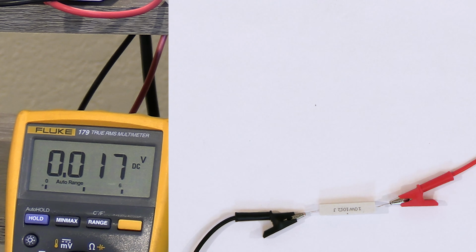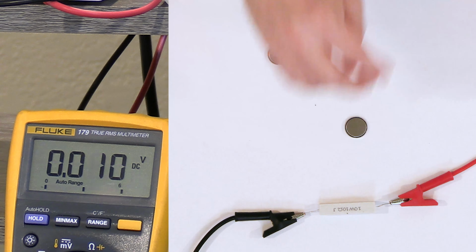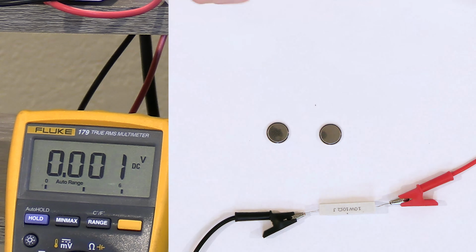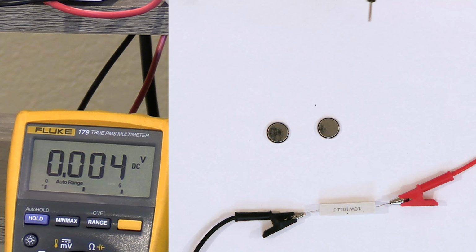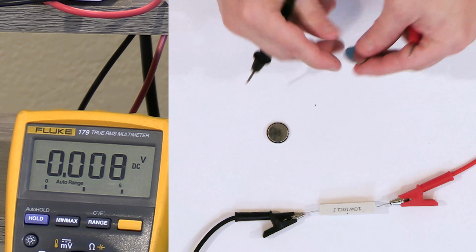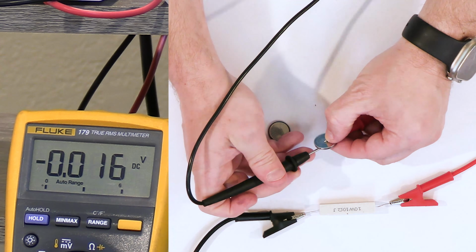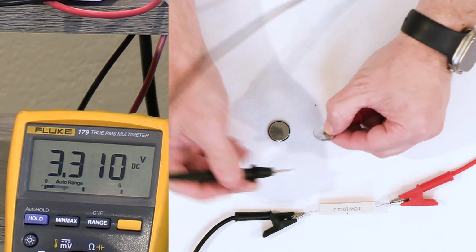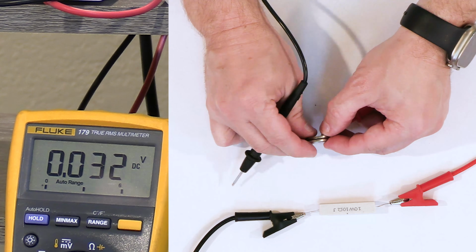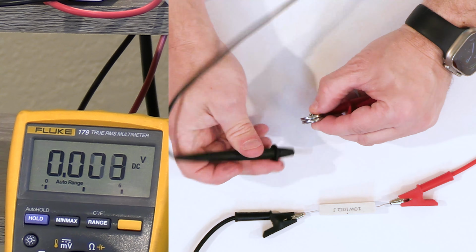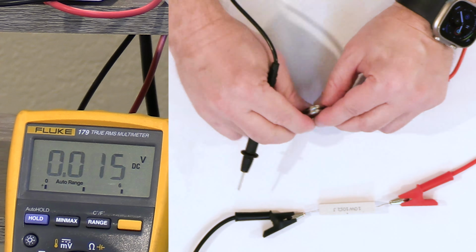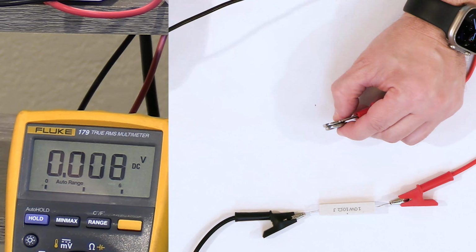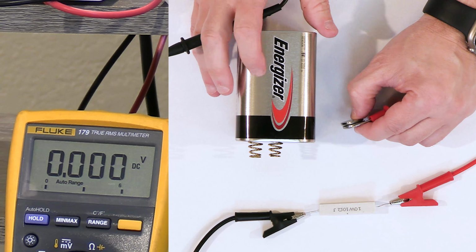And then finally, these little batteries, let me get them out here and put them out in front here. These little batteries are used in very small devices, right? Calculators and things like this. Each one of these is not 1.5 volts. Each one is 3 volts. So what I'll do is I'll just put one side on one and the other side here, and we'll see it's just a little bit over 3 volts. So if we stack 2 of them end to end just like this, we're stacking the mountains together. And what do we get? Just a little bit over 6 volts. So these 2 batteries stacked together is 6 volts. This gigantic battery here is also 6 volts.